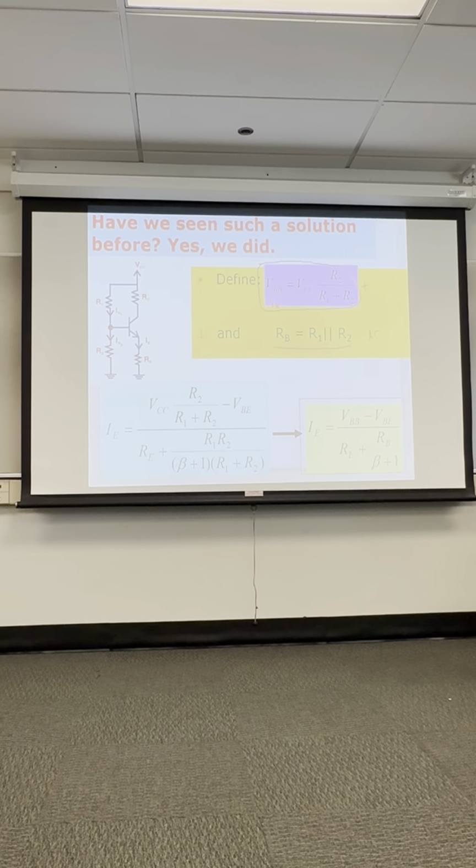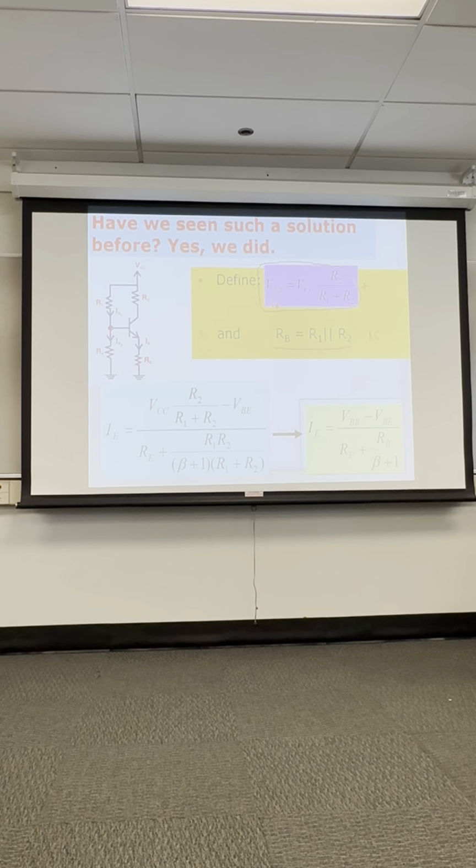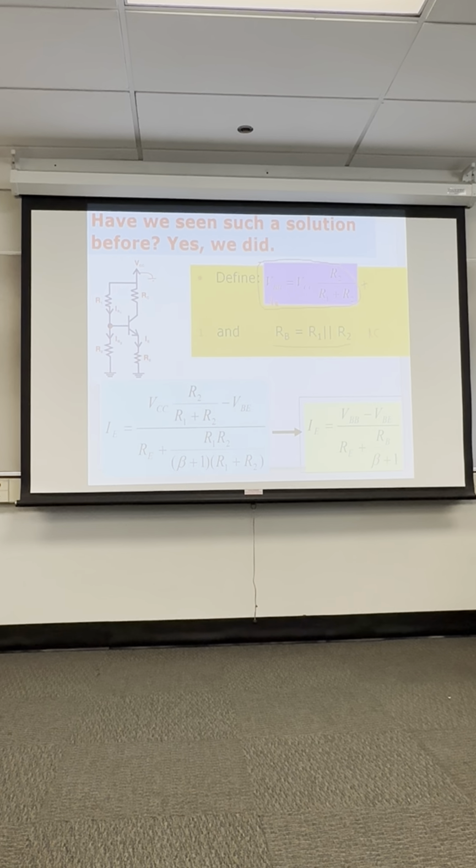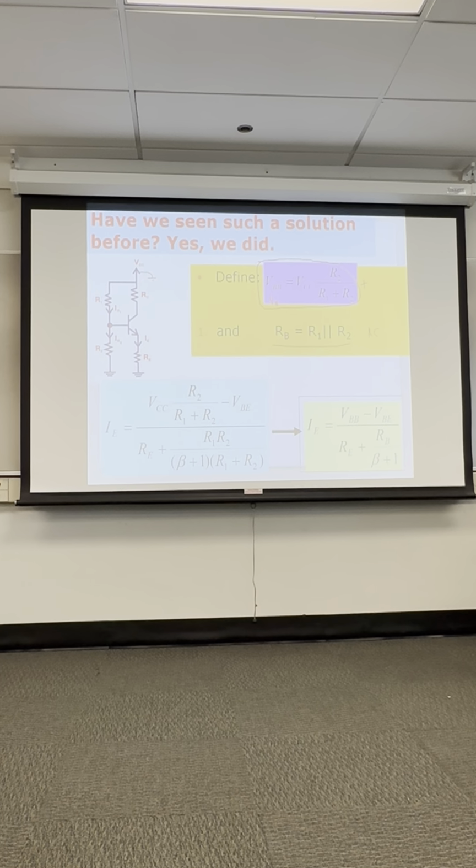Whenever we solve for AC, this battery becomes a short circuit, wired to ground. So now you've got two resistors in parallel, and now we can make this assumption here. What it's doing is moving toward what's called a small signal assumption. So we can get those two resistors in parallel.